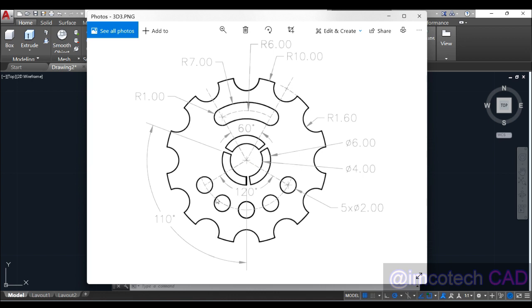So we are going to take the radius of this circle. Let's look for it. You can see the radius is 6 units. Look, that is the same circle. Okay, the radius is 6 units, so let's get that drawn. And there is an angle of 120 degrees on this part. So exactly what we did just now to get this angle, let's try to do that again. We will draw a vertical line and make an angle 60 degrees here, make another angle 60 degrees here. Although we don't need to do both sides if we're going to use just one circle. So I'll draw a vertical line, make an angle 60 degrees on this point. But first draw a circle of radius 6 units,